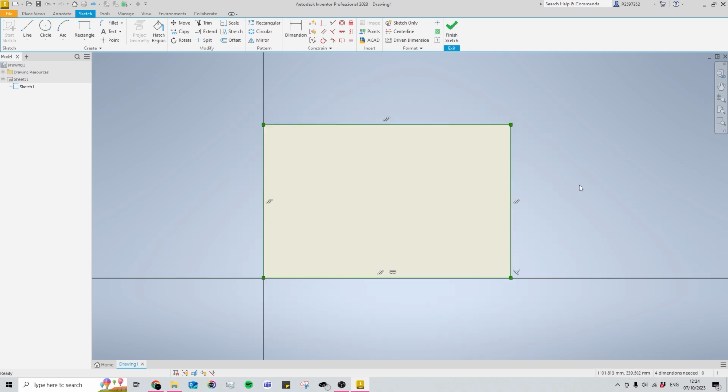So this border allows us to sketch geometry off of the page extents as if it were a line, meaning we can snap lines to the edge of our page. And also we can find center points on our page too, and that's the screen dot here. So we're going to interact with this using the offset tool. Press the O hotkey or select the offset tool and interact with the rectangular border you have just drawn. Define your drawing border by clicking or typing in a value.